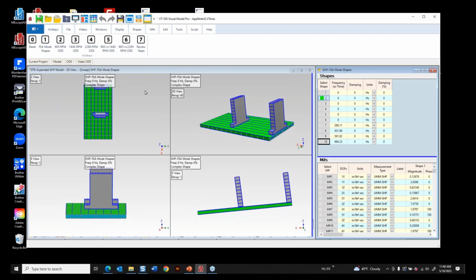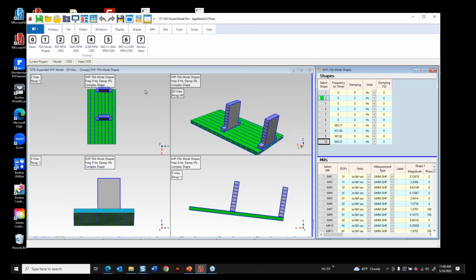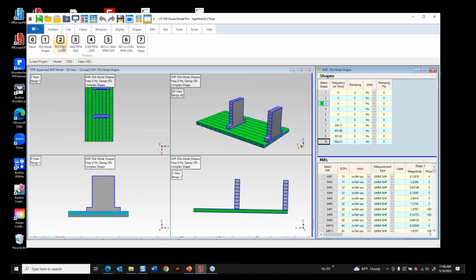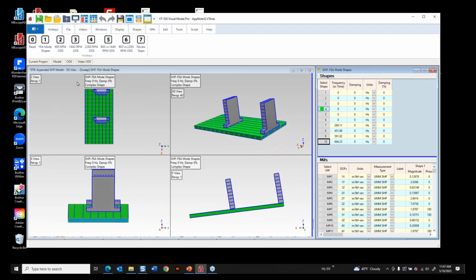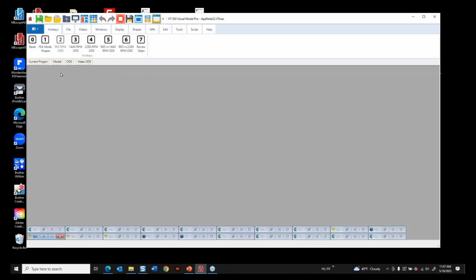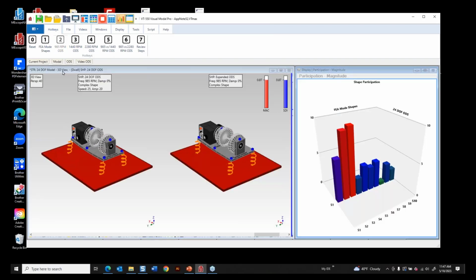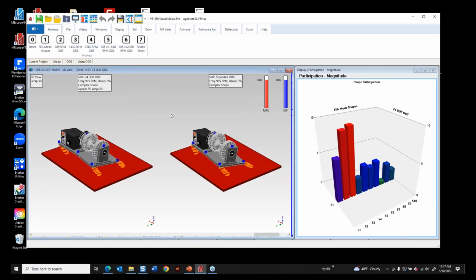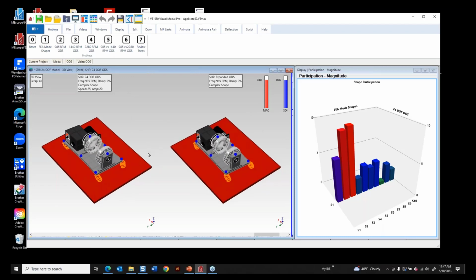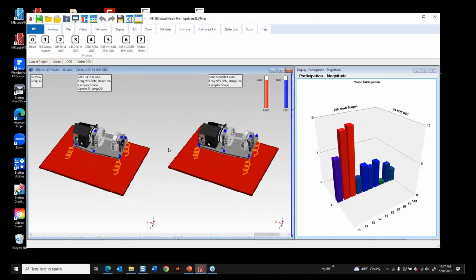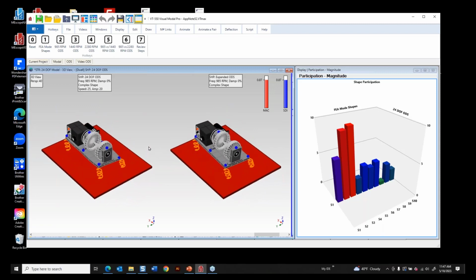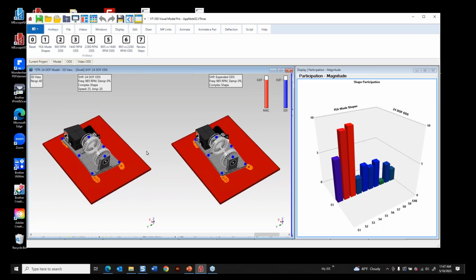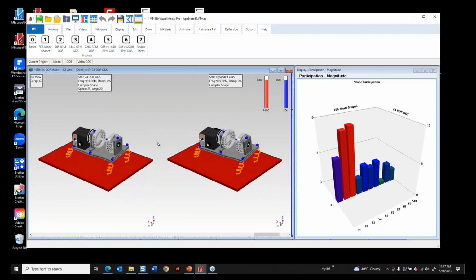And as we said, with a fundamental law, all vibration, and again, the ODS that we measure from the real machine is a summation of these mode shapes. So that's what we're going to prove here by curve fitting those 10 mode shapes to the experimental ODS data. So here's a picture. And over here on this side, we're looking at the machine being animated and the rotors are going around and so forth. And we got some springs modeled underneath the machine.